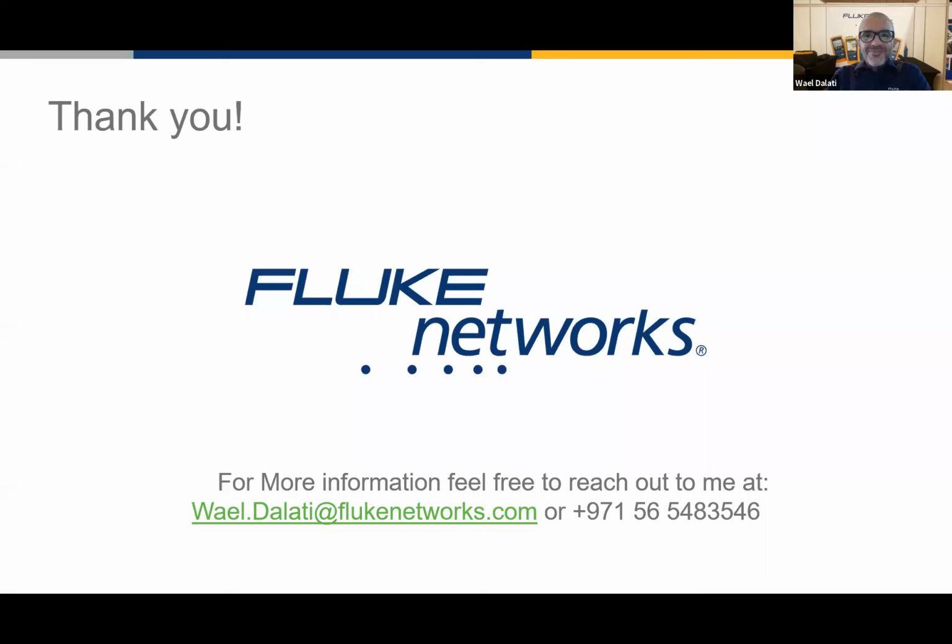Another question, and maybe it's a repetition. Someone asked to tie a fiber optic cable between two passive racks, only 250 meters from each other. Is the light source power meter enough for certification, or do you also need an OTDR? This is one of those questions where we like to say, it depends on the contract and what the end user is asking. If you are in a data center and your intention is to transmit 400 gigabit Ethernet, you may have an interest in knowing the reflectance of those connectors, which would require an OTDR test. But if you are just required to do the loss testing, a light source and a power meter, as Wael mentioned several times, is the tier 1 or the basic requirement for loss testing.